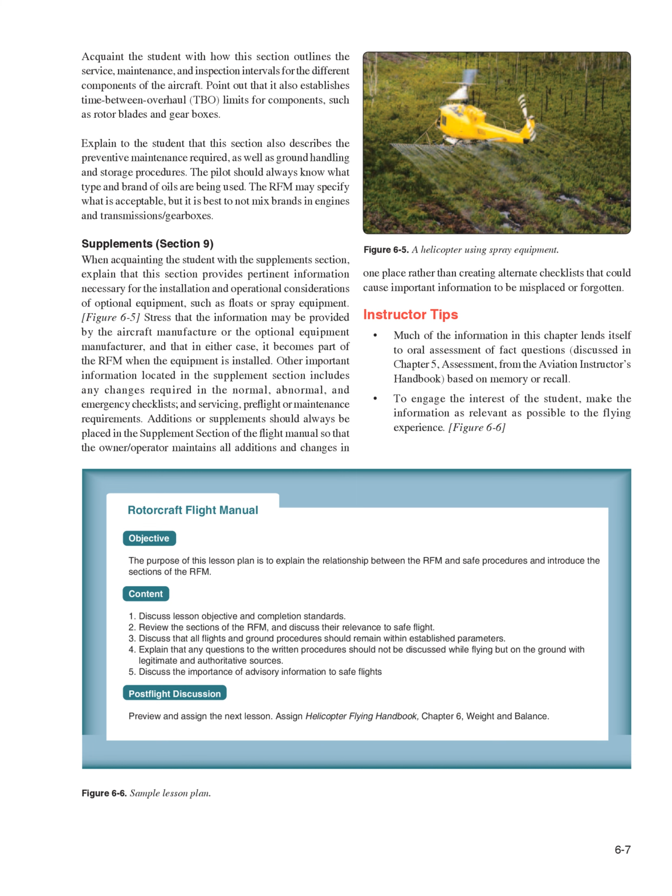Other important information located in the supplements section includes any changes required in the normal, abnormal, and emergency checklists, and servicing, pre-flight or maintenance requirements. Additions or supplements should always be placed in the supplements section of the flight manual so that the owner/operator maintains all additions and changes in one place rather than creating alternate checklists that could cause important information to be misplaced or forgotten.